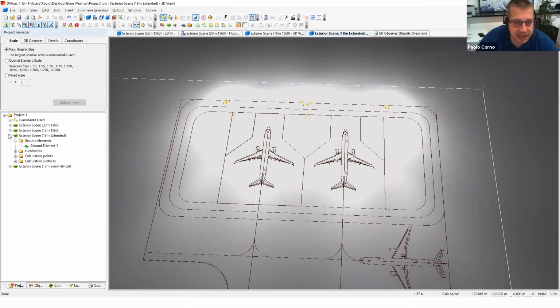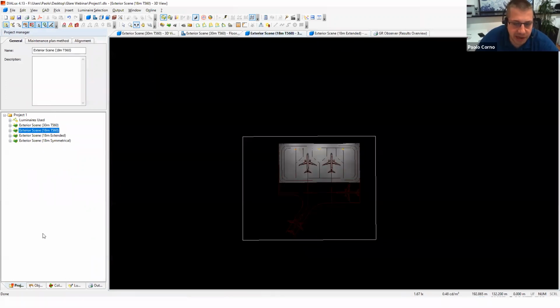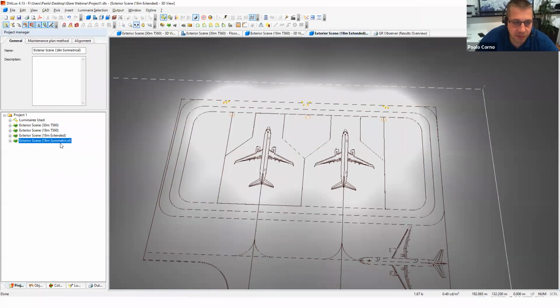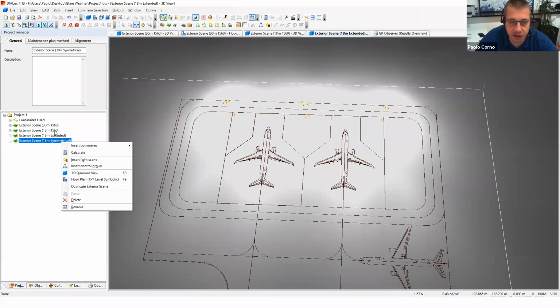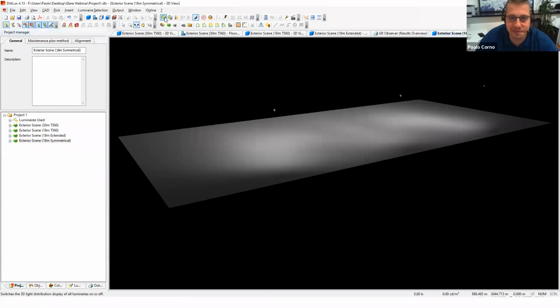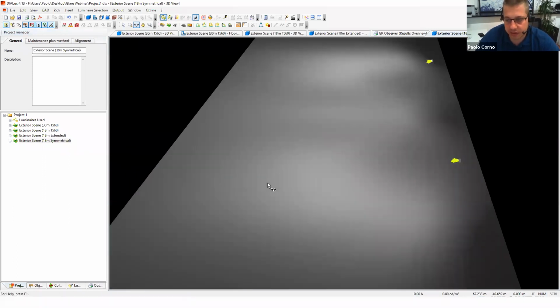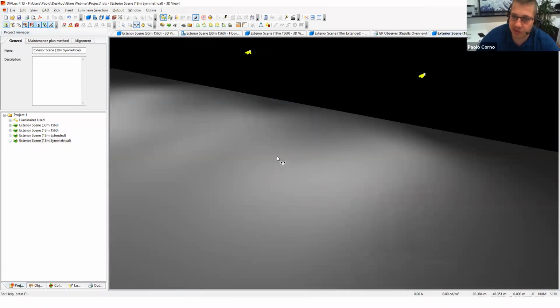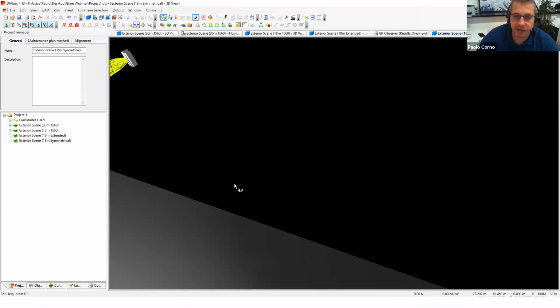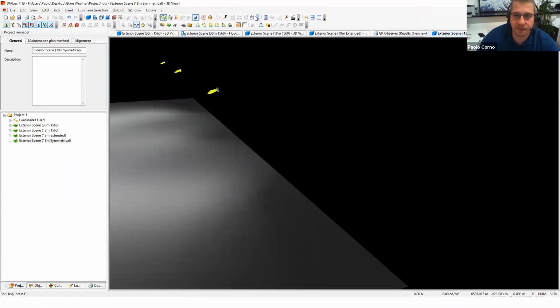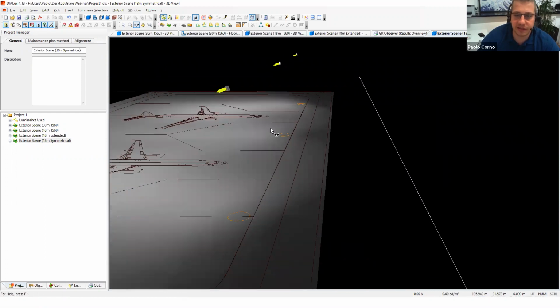So we've taken the exact same configuration with the 18-meter masts and the same number of floodlights, but instead of using our FH asymmetric optic, we're going to be using a symmetric optic, something you would probably see on a sports field. So you can already see visually what the difference is.